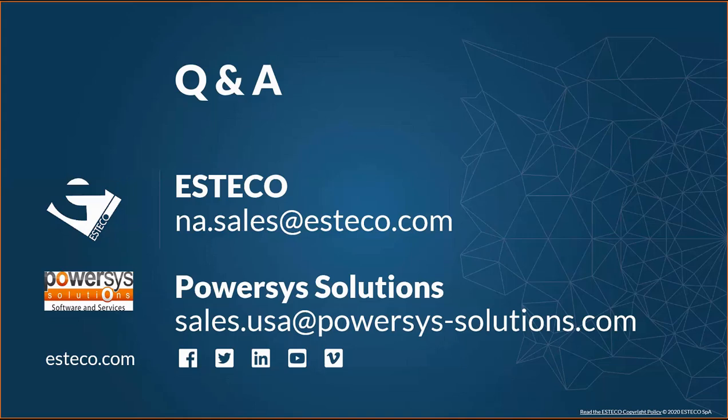Now the next part of the question, if it can be optimized, I think that's more nuanced in a sense that it comes to the same problem as the number of layers in the rotor. Can we create the number of strands as an individual parameter? That comes down to how we set up the geometry itself. But if we set the number of strands, and define the position of the strands and the shape of individual strands, and how that impacts proximity and AC losses, yes, that can definitely be done.